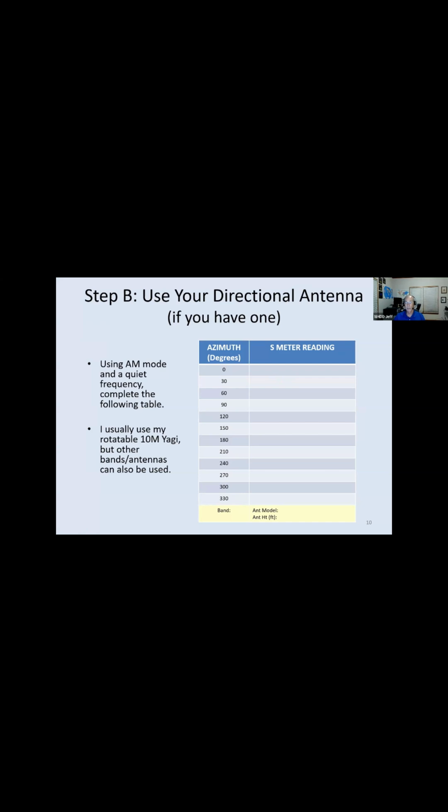It also many times tells us there's more than one noise source. You might hear something at 60 degrees, and then you see another peak at 210 degrees. Usually when I get involved, it's not a simple case of the noise being across the street. There's a lot of stuff going on, and I've seen 2, 3, 4, even 5 different noise sources, kind of confusing the issue.